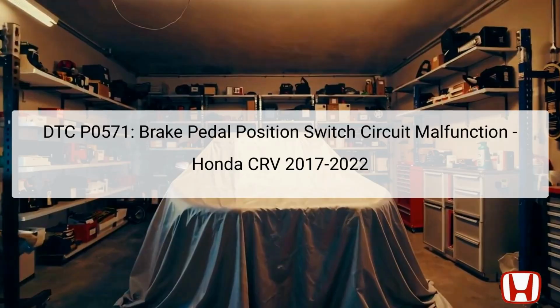The diagnostic trouble code DTC P0571 indicates a malfunction in the brake pedal position switch circuit. This error can lead to critical safety features of the vehicle being compromised, as the brake pedal position switch plays a vital role in communicating the brake status to the vehicle's powertrain control module, PCM, and other systems.